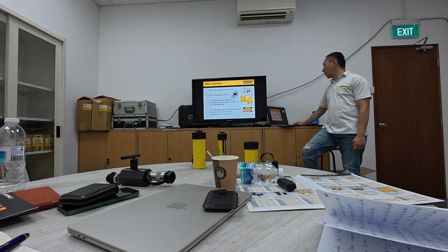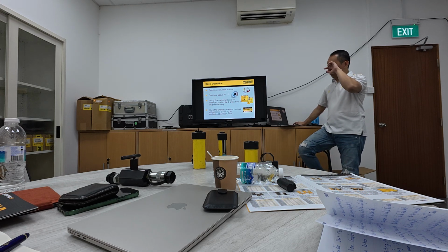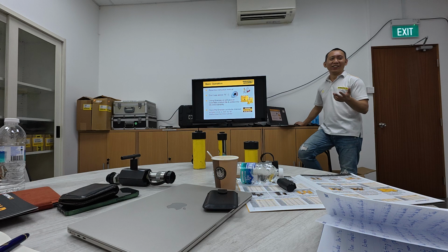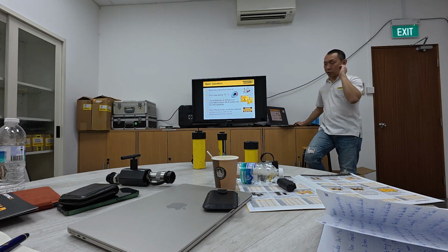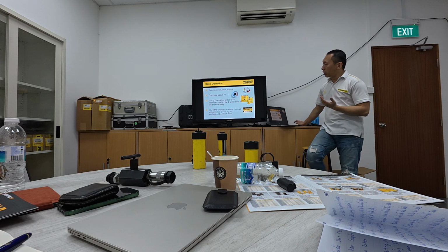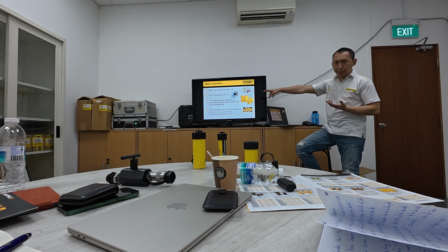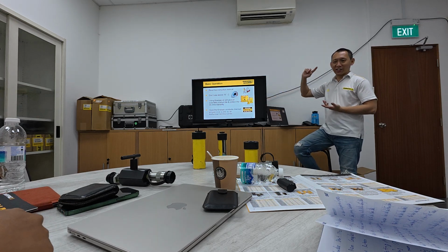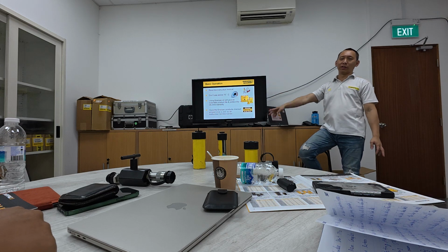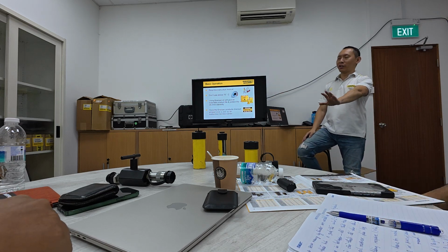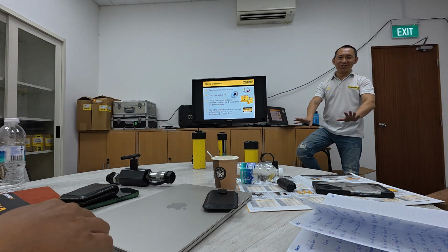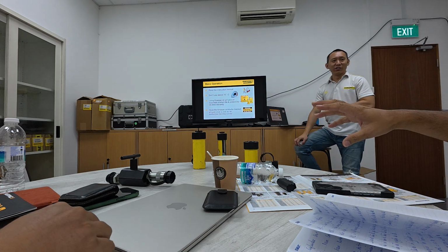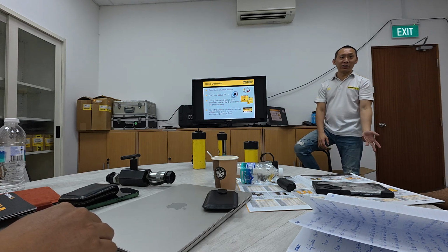So for basic operation, of course we always encourage you to tell the user to read the manual. Usually people don't read. You can always download the manual from the website. To use over 70 degrees Celsius, use ENERPAC oil. The customer says, I want to use my own type of oil. You tell them, okay, you use your own type of oil, no problem, but no warranty. No warranty for the pump and cylinder also. If they use their own type of oil, then of course no warranty.